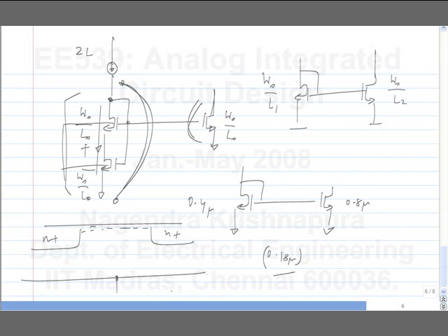So if you think of this as the upper MOSFET and this as the lower MOSFET, the backgate here is connected to ground and here also it is connected to ground. So that's how it should be. In fact, if you take this backgate and connect it to source, it is not equivalent to two MOSFETs in series. Is that okay? So only if you connect it to ground is it equivalent to a single long MOSFET. See, if you connect it back to the source here, that means that somehow this backgate is connected to this point, in the middle of the MOSFET. That's not what really happens.